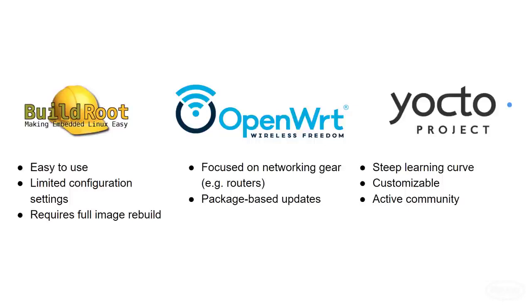OpenWRT focuses on mostly networking gear such as routers. As a result, you might not find many tools and support for creating generic Linux images. Additionally, many of the images it creates are based around the concept of users updating the device themselves through a package manager. This can make it a little more difficult if you're trying to create a whole fleet of embedded Linux devices and want to push updates to them.